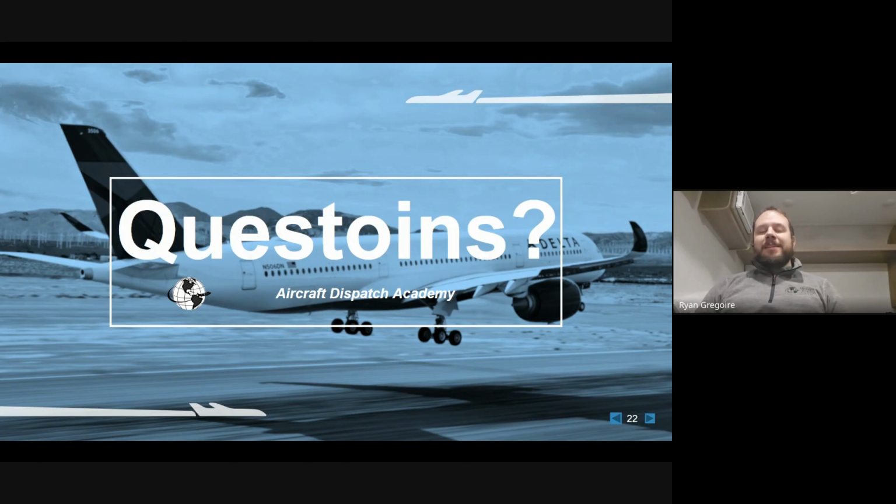That's an MEL that ends either at the end of the Z day or the end of the operational day, depending on how the MEL is written. Hopefully, whoever is doing the routing of that aircraft has taken into consideration that it has an MEL that will expire at the end of the day. But you will regularly see MELs on aircraft that are flown all the way up to their limit. And then usually, even then, a lot of times maintenance control will get an extension on it.